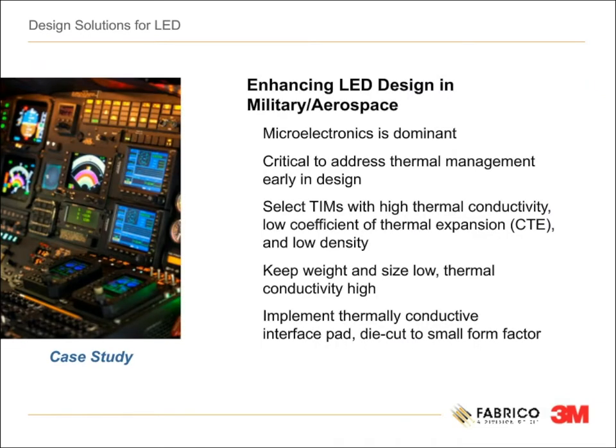In aerospace, everything is driven by size, weight, and power. Microelectronics get smaller, faster, and more complex with each new design. In this application, the key to our customer's success was selecting a low-density thermal interface material to complement their substrate's characteristics. The TIM also had a low coefficient of thermal expansion. The developed solution was die cutting a thermal interface pad to a very small, intricate shape. We also added a tab to the liner to make it easier to apply by hand.